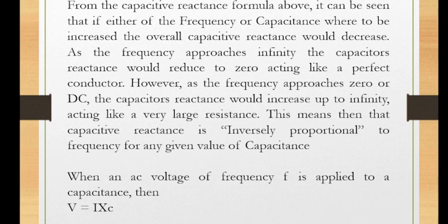The capacitive reactance will reduce totally. As the frequency approaches infinity, the capacitor's reactance will reduce to 0, acting like a perfect conductor. However, as the frequency approaches 0 or DC, the capacitor reactance will increase up to infinity, acting like a very large resistance. This means that capacitive reactance is inversely proportional to the frequency for any given value of capacitance, and that's so easy to know.